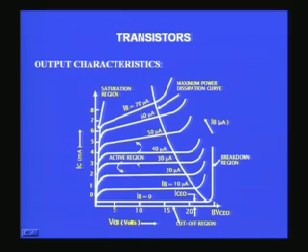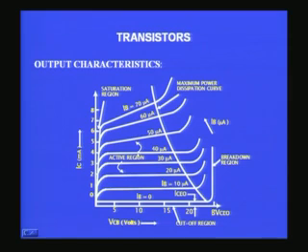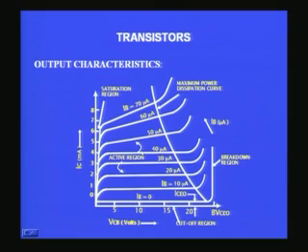And now what we have to do is, any given circuit can be positioned on the characteristics at a given point. So, this positioning of a transistor at a given point in the active region is called biasing, right. So, a transistor has to be biased to make it come to a very specific point, which is called the operating point or the quiescent point of the amplifier, and that is what we are going to now look at.